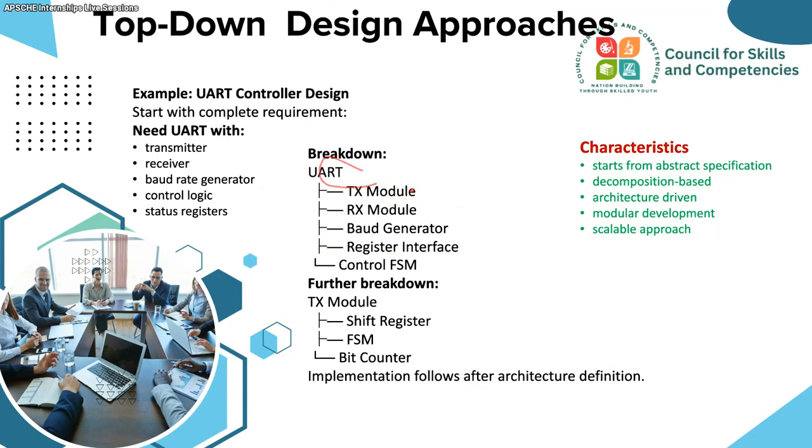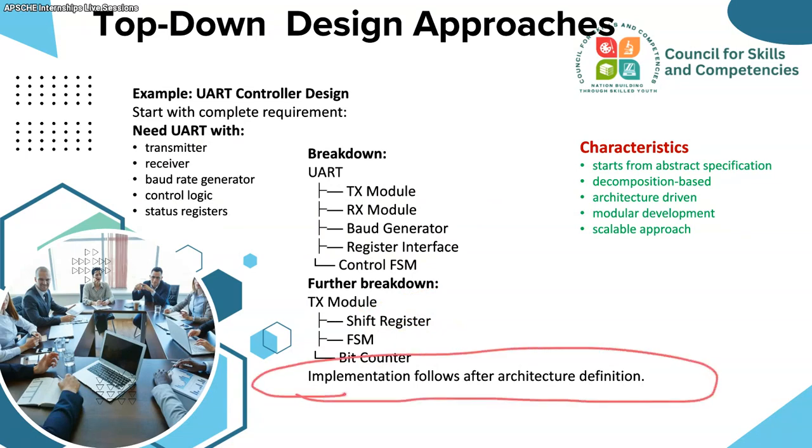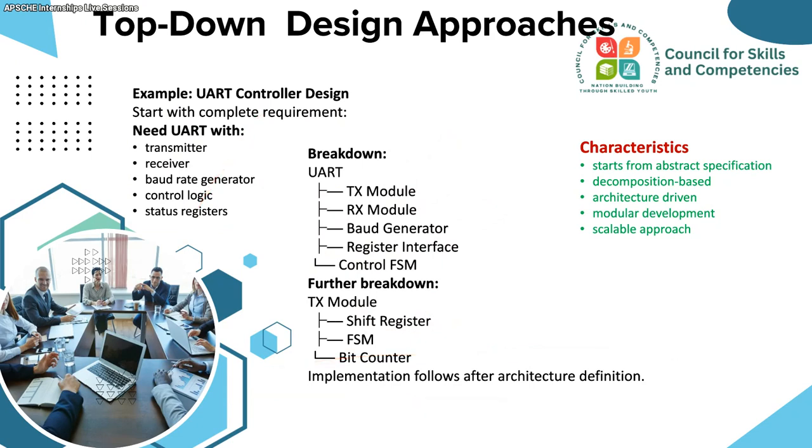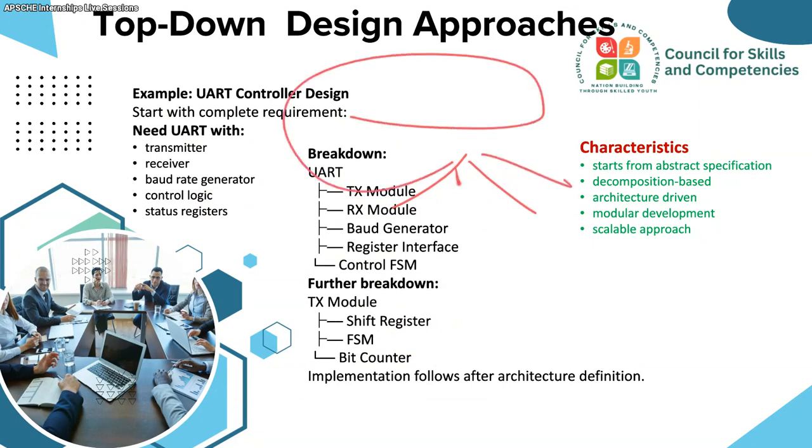In the further breakdown, we break down the TX module, RX module, baud rate generator, register interface and all those things. We go on to shift registers, a finite state machine, and a bit counter. This implementation follows after the architecture definition. First we define the architecture, then slowly we break it down from the top, and then we implement the hardware.